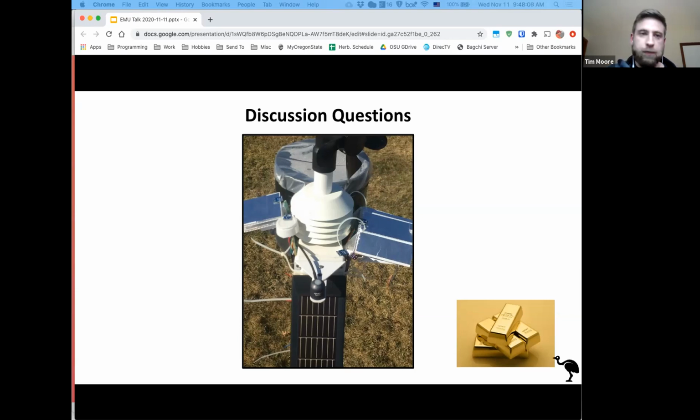Another potential solution some people are proposing is that you hook up a small computer fan that will actively blow air into the vane or the protective casing where you have your temperature sensor unit. That would activate a few seconds before you take your reading, then you would take your reading, and you would cycle through activating it. But of course, those types of setups increase the cost of anything that you're trying to do. They also increase the cost in terms of power usage, right?